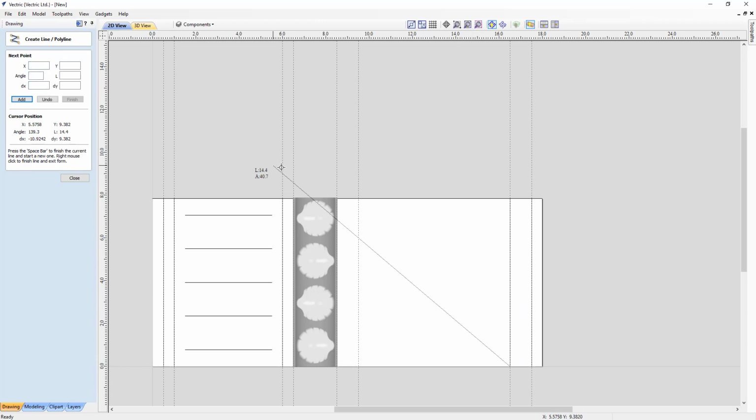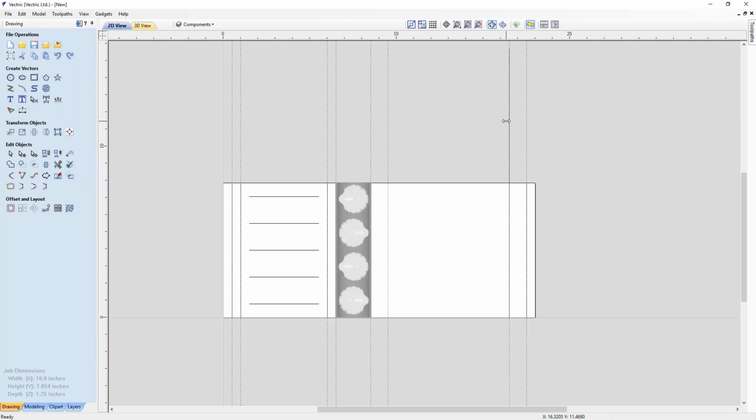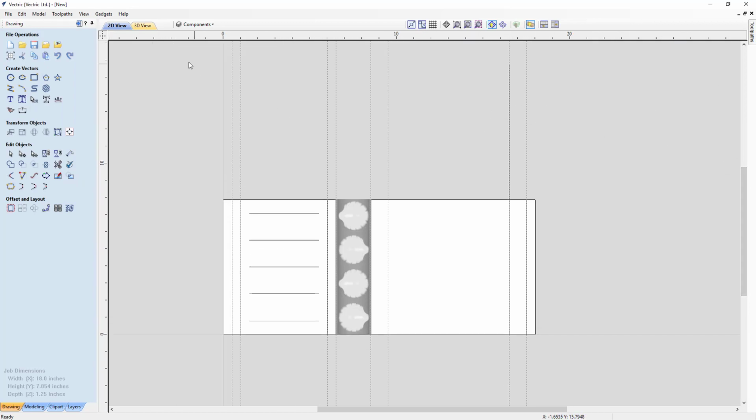And then we're going to go over to our form and fill out the rest over here. So we want it to be a 90-degree angle, and we want the length of this to be y times 2. And then if we go equals, we'll get the proper numbers. That's twice around, or twice the circumference of our cylinder. And we can just click add and close. It's hard to see, but our vector was created. If we hide our guides, we'll see there it is, and it's twice as long as our Y dimension. Let's turn back on our guides again.